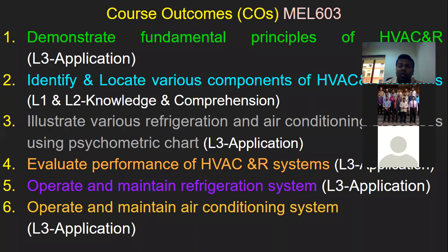You require some conditions, like pressure and temperature. Plotting means you should know the coordinates, and the coordinates will be in terms of properties like pressure, volume, and temperature. If you know the coordinates, you can locate that point, and once you know the final state, you can move from the initial point to the final point. Based on that, you can calculate the exit parameters for the process. So this is very much required.